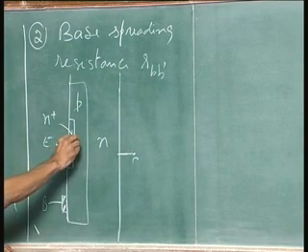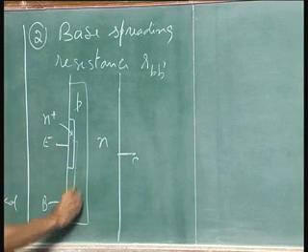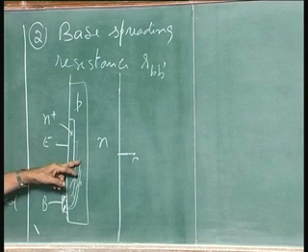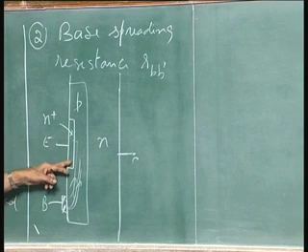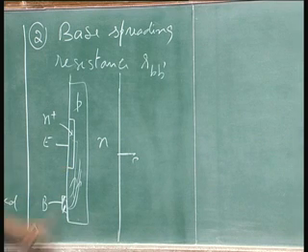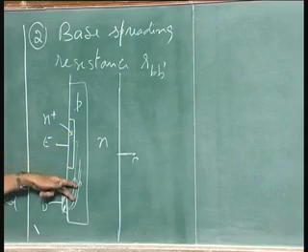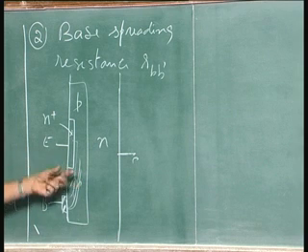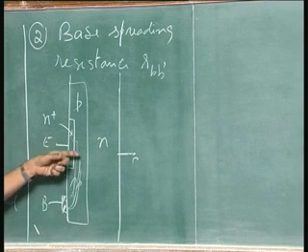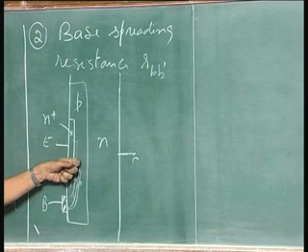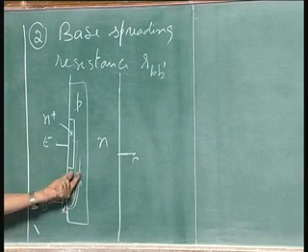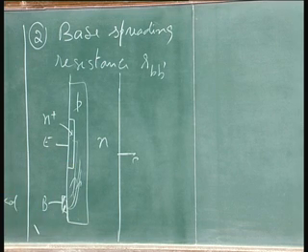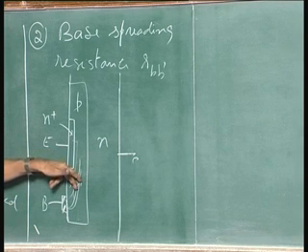Now, here the current flow is like this, laterally from the base, which supplies the recombination current and also the whole current to the emitter. The base current is lateral, and that is the one which sees this lateral resistance looking down. The resistance of that region is proportional to the sheet resistance of the layer, and the sheet resistance depends upon the thickness there, or to put it in simple terms, the resistance in this direction is more if the width is smaller.